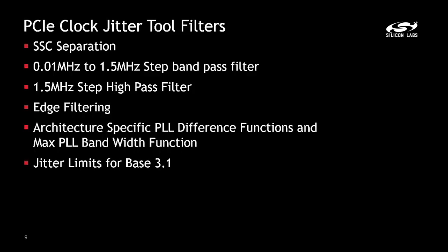A typical PCI Express system is the common clock architecture that considers a TX and RX PLL as well as a CDR. All three of these have characteristic transfer functions associated with it that determines how much noise on the clock is either transmitted, tracked, or attenuated.